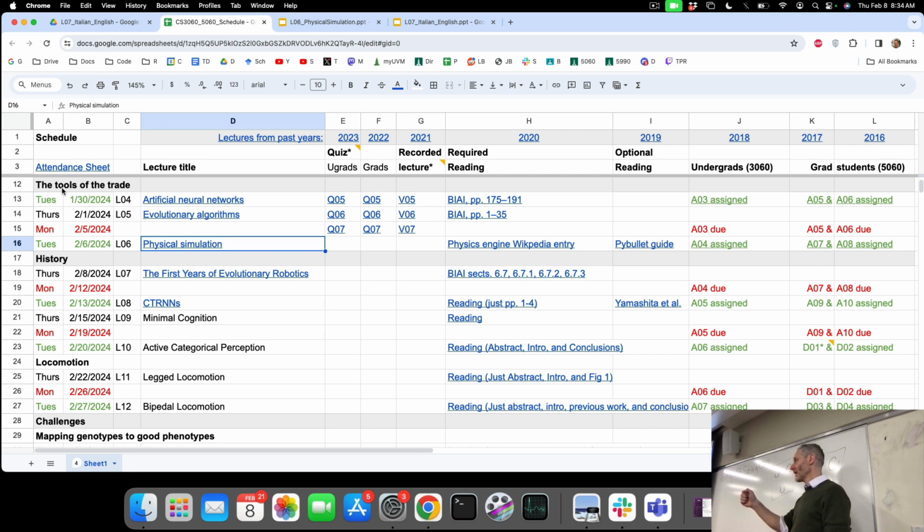That was a Braitenberg vehicle, and there were different motors, synapses, and all of them count as parts of the phenotype that are encoded in the genotype. If we're fixing the sensors and motors, and connecting this sensor to that motor with a synapse, that synapse has a weight associated with it, and that's what we're encoding in the genotype for the moment. So if we have 2 sensors and 4 motors, and we're wiring up every sensor to every motor, we've got 2 times 4, 8 total synapses, which is 8 synaptic weights.